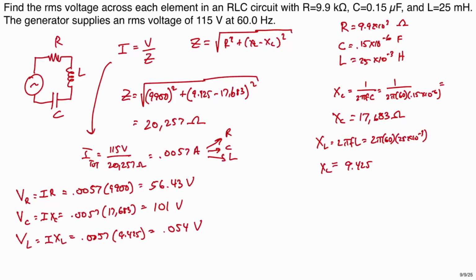Do the elements in these circuits, the resistor, the inductor, and the capacitor, wiggle at the same time in the same place? No, right? We're hiding the time-dependent parts of this circuit. And in hiding it, it seems like we kind of broke conservation of energy, but we didn't. Just because that's the average voltage, that doesn't mean at any one instant in this circuit, that's what the voltage is for that thing. At any one instant in this circuit, I can guarantee you that the total voltage across the resistor, inductor, and capacitor will be 115 volts.